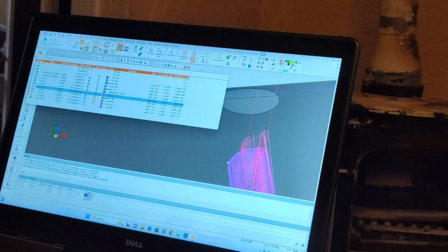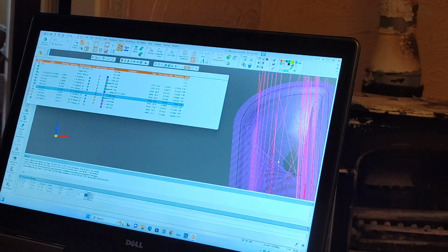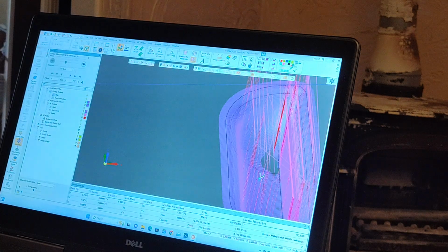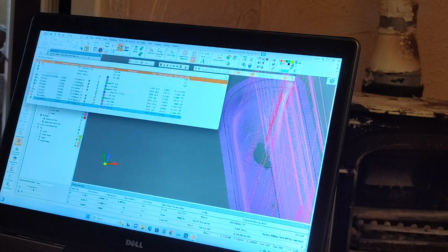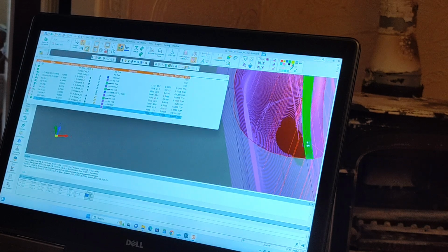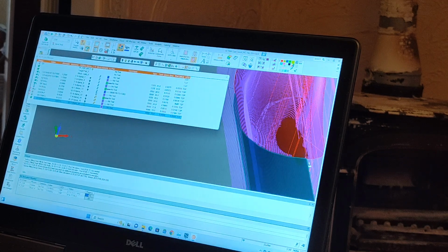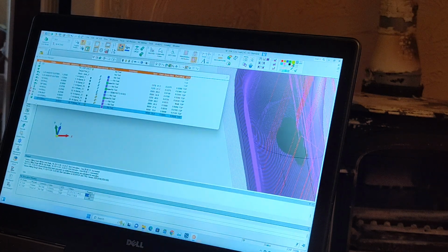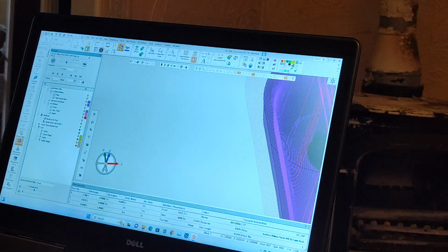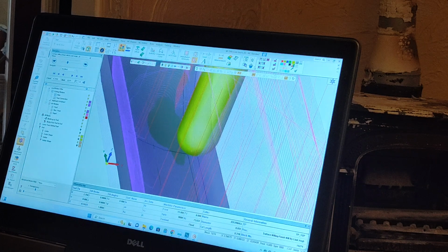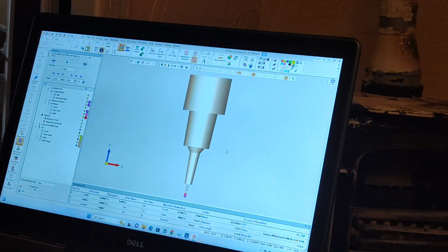And let's go back over here for a second. And we're going to go to the navigator. Or wait, no, not yet. First, we're going to just pick a couple of faces here. And then hide other. And then go to the navigator. And then go to our front view.